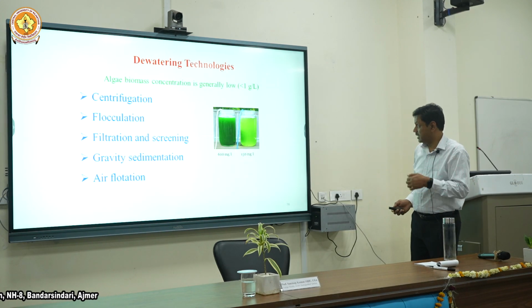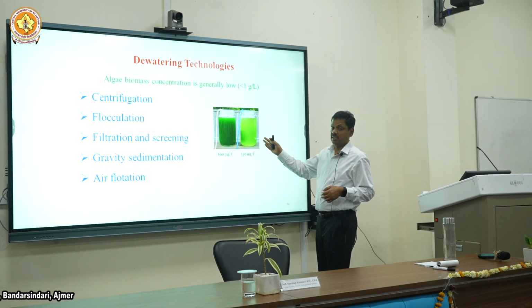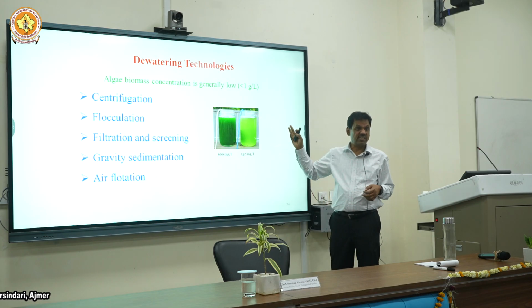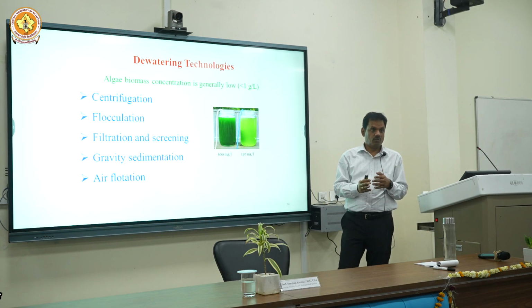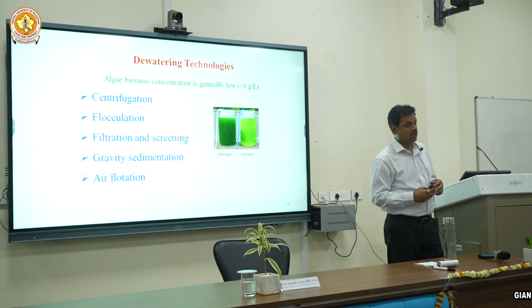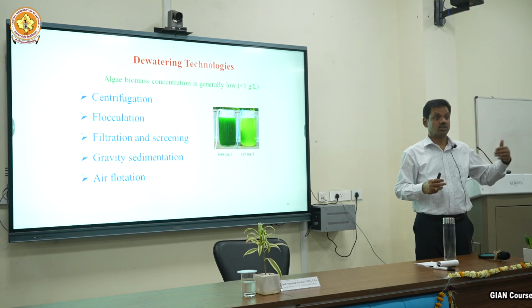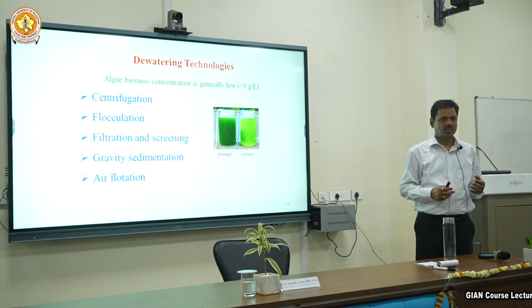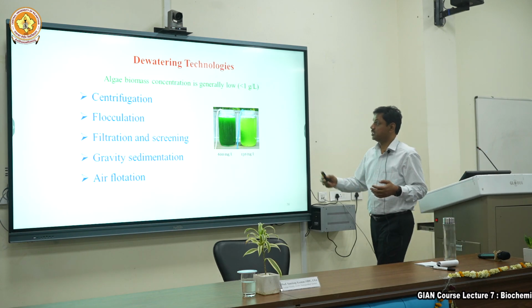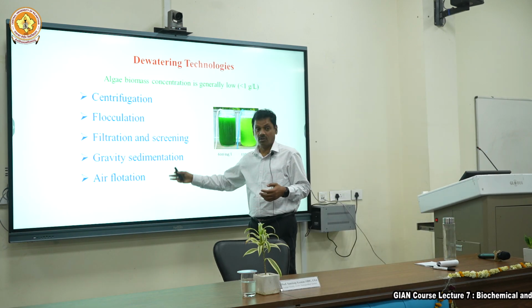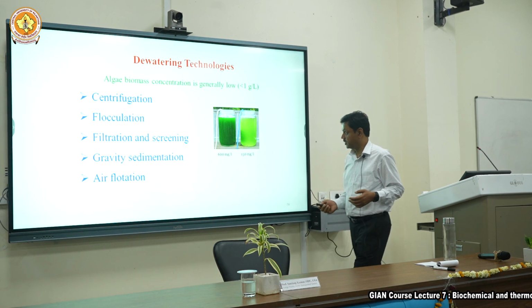So dewatering, even if this is dilute and it's fine, hydrothermal needs very little water. So you want to concentrate it to meet techno-economics. You are not needing just water. So maybe 8-10% you want to concentrate. For that we do centrifugation, flocculation, and all those things. Different options.